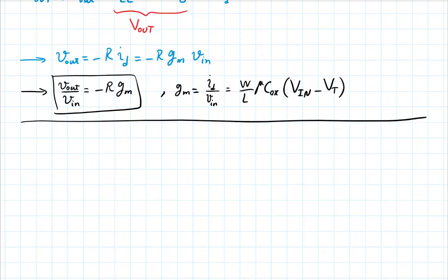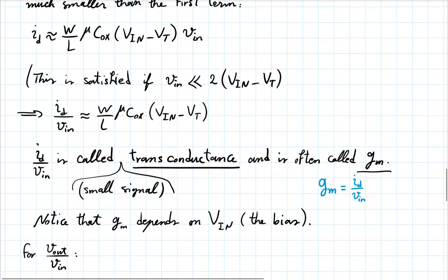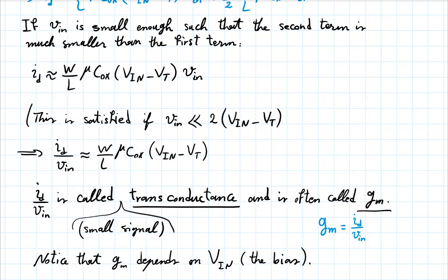Let's take a short break. I want to do a quick graphical representation of what we talked about here. Think about the fact that here we calculated this transconductance, this GM, for that MOSFET, right? And the circuit was very basic. There is really just a MOSFET there and a resistor there. This transconductance didn't depend on that resistor. It's just as long as we are in the saturation mode for the MOSFET.